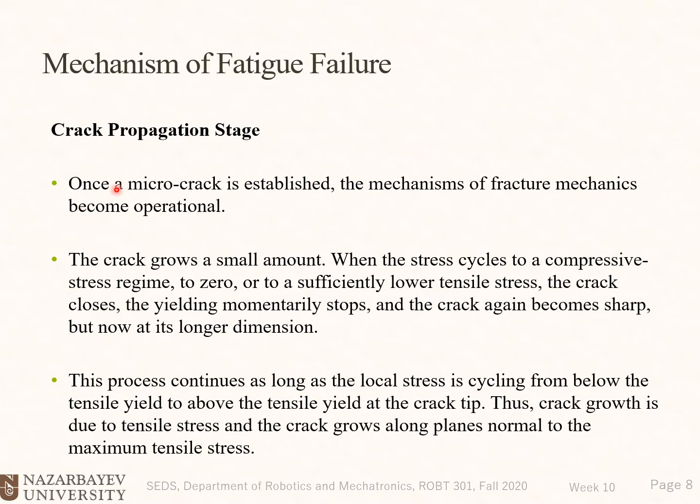Okay, so we have this microcrack develop, then we have a cycle of stress goes from positive to negative. But when it goes to the negative and zero, we have a compressive stress. That compressive stress closes the crack. Okay, then we will have sharper edges, and now we have a high stress concentration and it is ready for the cycle of stress to go positive.